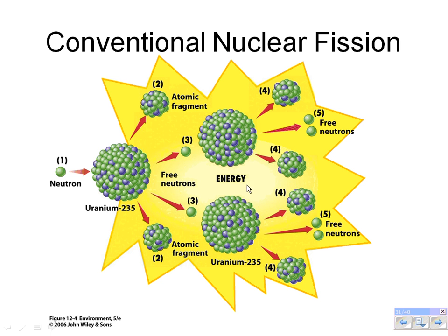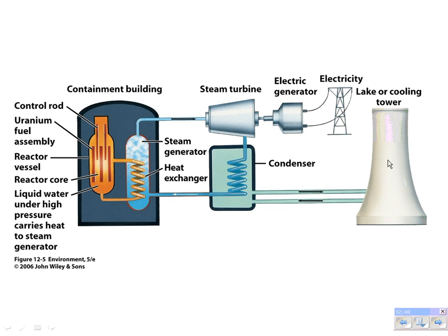We look at our nuclear power plant. Don't forget the different parts of a nuclear power plant. Something that we have now that we did not used to have is a containment building. This containment building is a 3 to 5 foot wide concrete building which protects our reactor core where the nuclear fission reaction is taking place. If you remember the accident in Chernobyl, there was no containment building. So this is a safety measure.